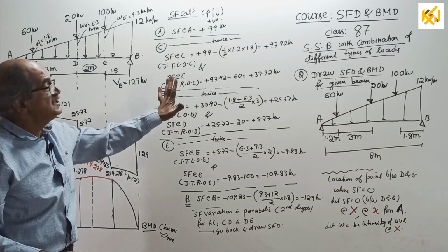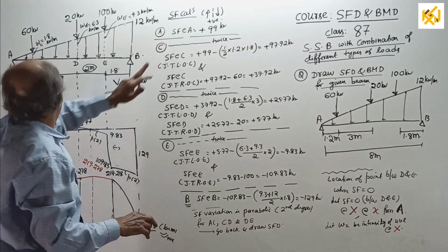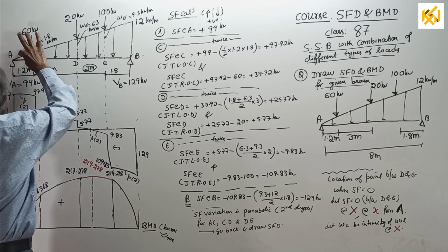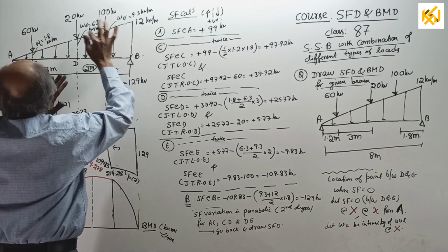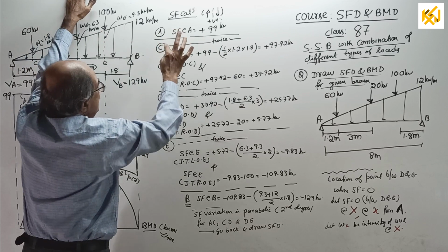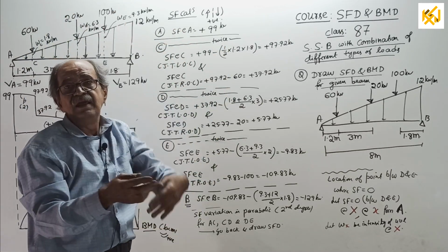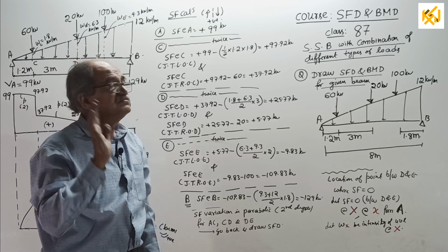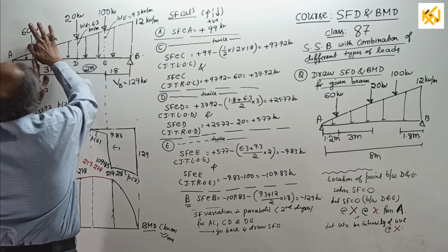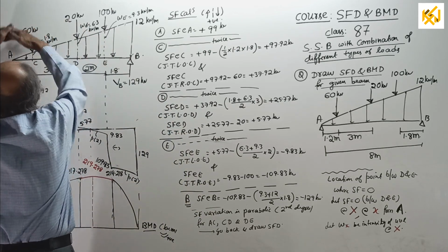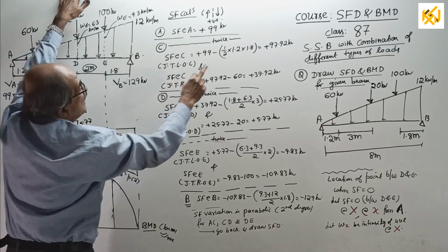Now, or systematically, shear force at A, slightly come inside. Look this side, plus 99. Shear force at C, D and E, you have to make a note. Point load is there, so shear force calculation twice. Okay, start. Just to left of C, plus 99 minus this much load. I have written here.